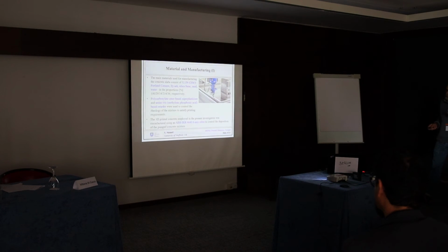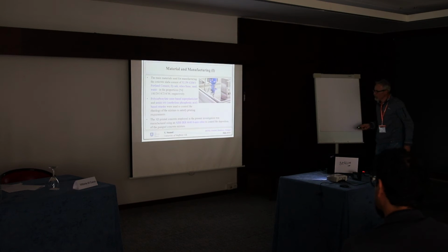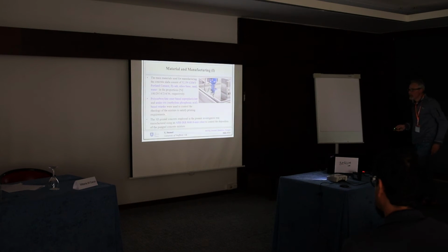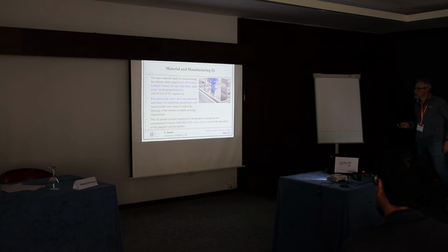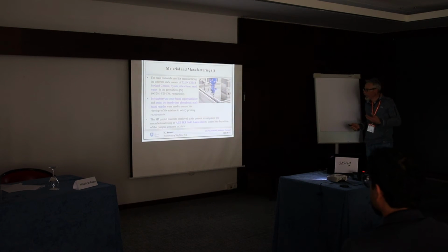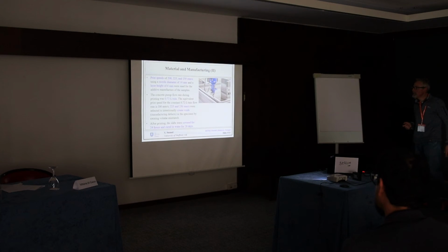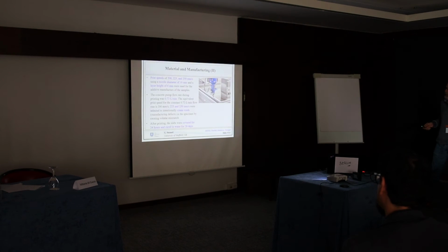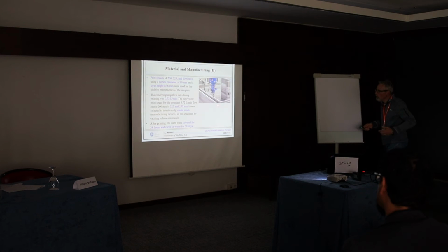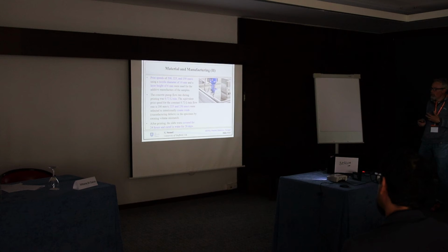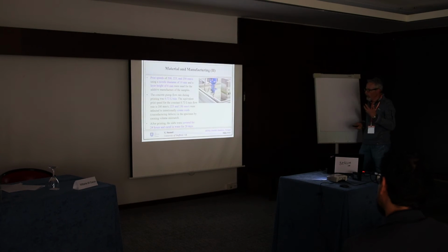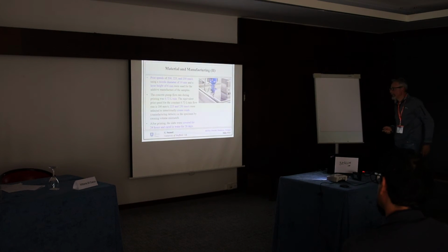You needed to use a suitable superplasticizer, plus you needed to use a proper retarder, so you give the process plenty of time to settle down after extrusion. You needed to control the whole process in quite an accurate way using a specific rod, and this is what we did. Plus we changed the print speed and also the volume of concrete that was extruded throughout the process, and after doing that, all the specimens were cured, covered for 24 hours and cured for 28 days.